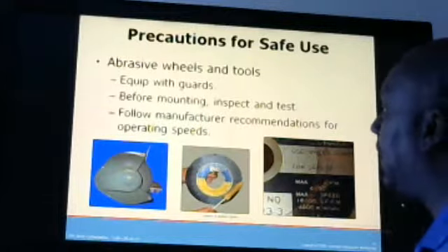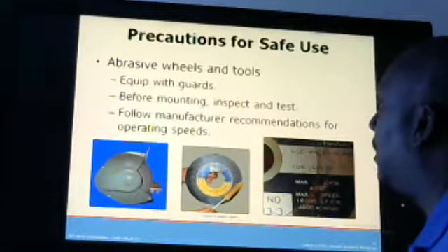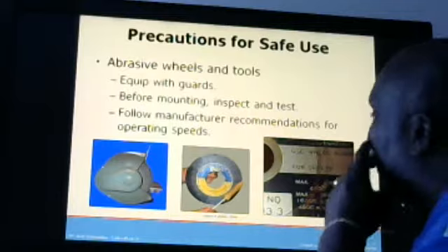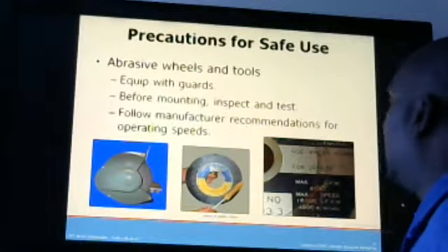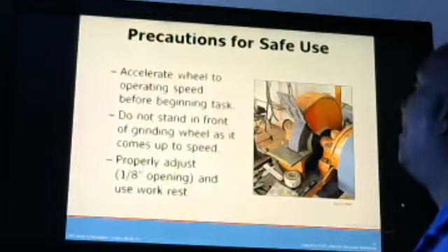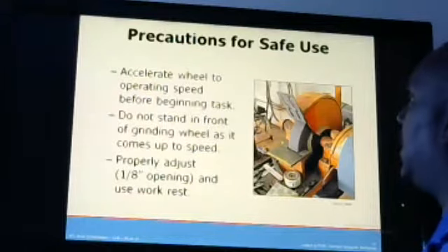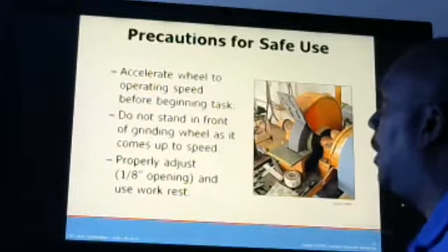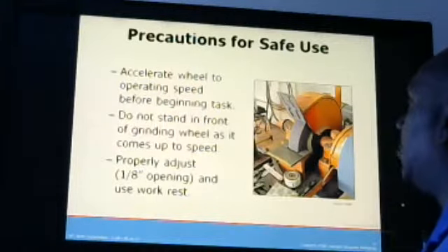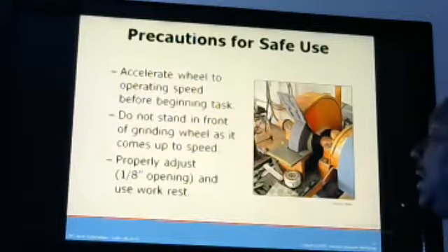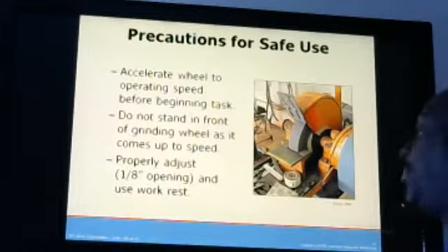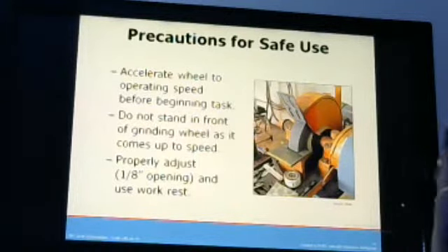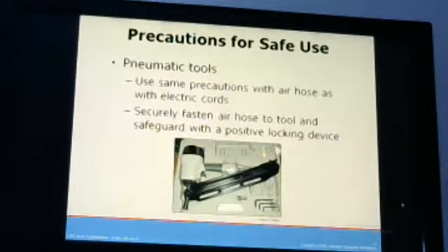Precautions, you want to tap the wheel to make sure that it's not broken before inspecting, following your manufacturer's recommendations on that. Accelerate the wheel. Let the wheel come all the way up to its speed before beginning your task. Don't stand in front of a grinding wheel. Let it come up to speed. And the proper adjustment of 1/8 inch is used on the work rest there.